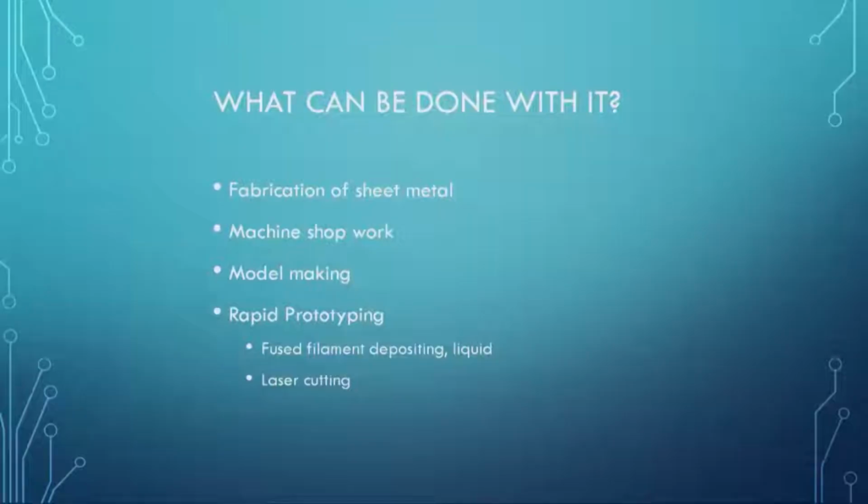Second thing is, in the machine shop you end up having to work with other hardware, typically how to mount things like connectors, whether you need to make some spacers, bosses, and D-shaped openings. All these are best handled with CAD. So if you have an EDM or a wire cut device, any complicated shape can easily be done. Later on in the lecture I will show you samples which you can do.